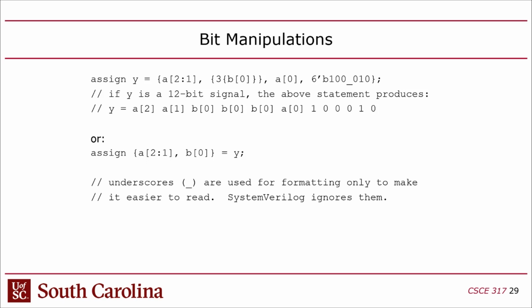When you look at the FPGA boards, you can see the LED getting brighter and dimmer, but is it just an optical illusion that it's getting dimmer because it's really just turning on and off faster than your eye can perceive? The duty cycle determines how long it's on versus how long it's off. Which is it? Or is it really getting dim?